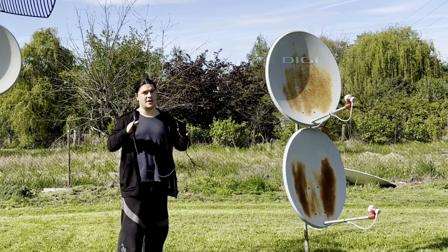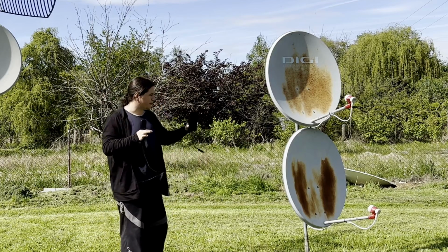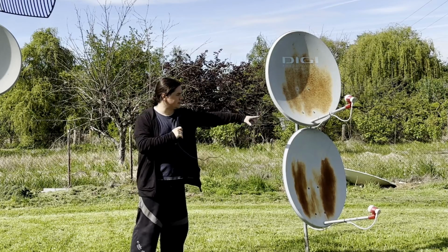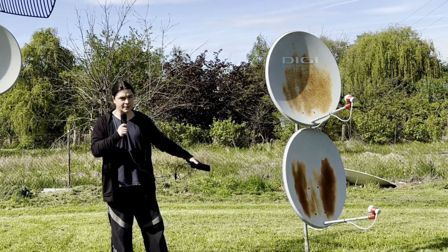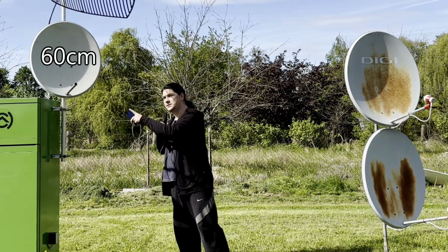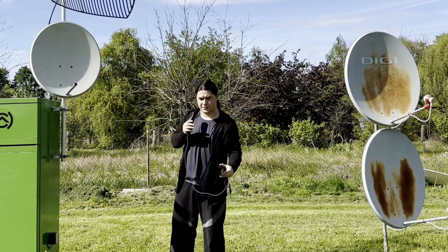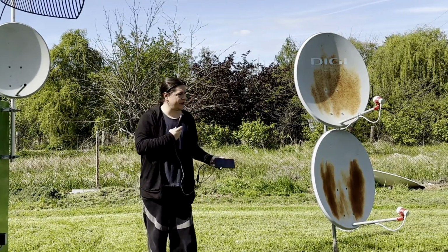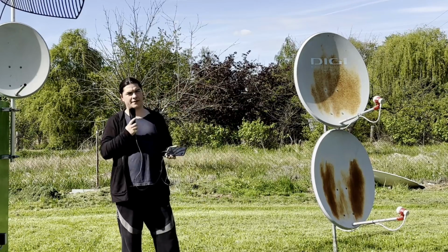You will want to have a higher gain antenna. I would say an 80 centimeter dish like this, like one of those, would be ideal because it's not too big. Something like this works as well. This is also enough to peak the strength of the transponder. You want to make sure that the LNB you are getting can receive 10.5 gigahertz.